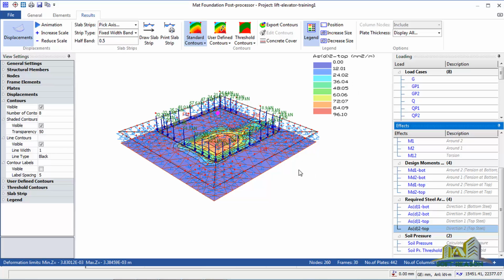Alright, so this is the design. Let us check the soil pressure. You click on this soil pressure, you can see the graph. Now it is okay. You can see the soil pressure 169.231, less than 224. If the value you're having here is greater than the value you're having here, it means the soil is already failing. It's not able to hold the foundation. But we can see the critical highest point here, which is 191.506, which is even less than the 224. So the soil is okay.